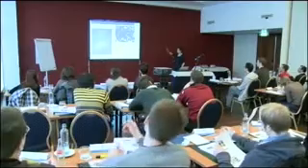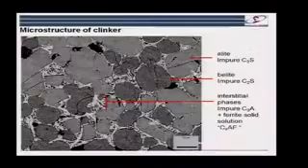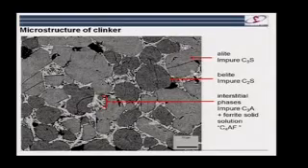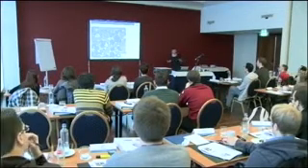And then if we cut through those grains and see what the different phases are, what's very important is that each grain usually contains several of the cement phases. So if we just go back to this slide here, when we grind the cement, it doesn't fracture neatly around the edges of these crystals. It fractures through these crystals. You can actually see these cracks here brought about by the thermal cooling.